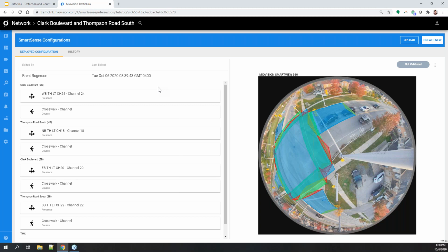It also lets you have an audit trail on who's changing your configurations, which is an important thing if you have more than yourself in there changing configurations. You want to be able to point to who touched it last. This is a common practice in many traffic cabinets, and I often see it in the form of logbooks or controller passwords, whatever it may be. Logging with audit trails is important, especially if something not ideal is occurring and you want to figure out why is that occurring or who started that and how do we finish it.